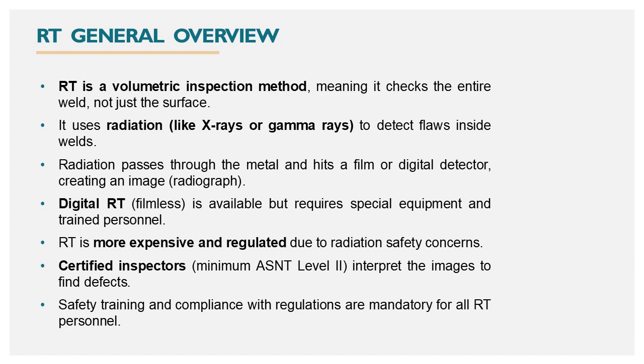RT is more expensive and regulated due to radiation safety concerns. Certified inspectors, minimum ASNT Level 2, interpret the images to find defects. Safety training and compliance with regulations are mandatory for all RT personnel.